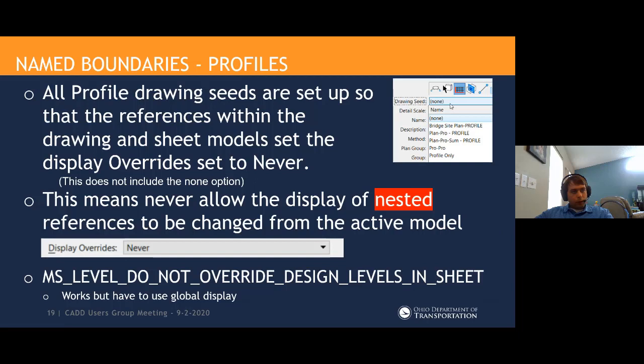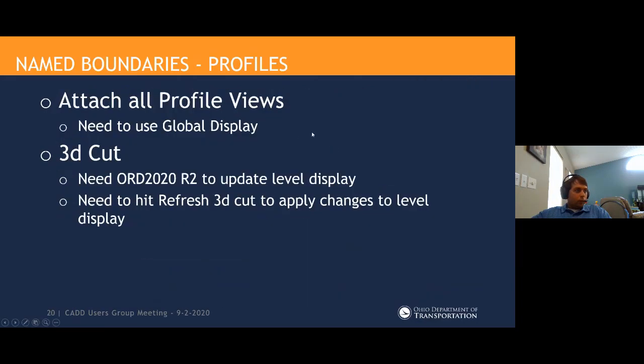Profiles are set up in a very similar manner. As long as you're using one of our seed files for profiles, the display overrides is set to never. This one also, I'll talk about the do not override level as well, and having to use global display. So let's get into this.